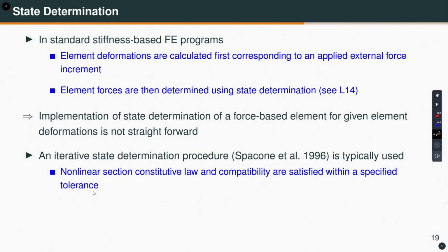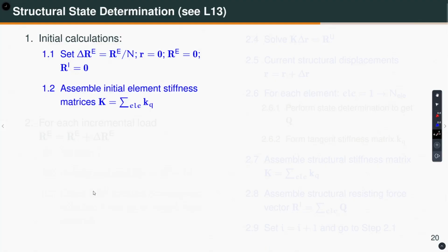The nonlinear section constitutive law and compatibility are satisfied within a specified tolerance. Although I said that in this course we will not be focusing on the implementation, I think it is a good idea to get at least some understanding of the implementation of this force based element. So, let me go through how the state determination is done at the structure level and then at the element level for a flexibility or force based element.